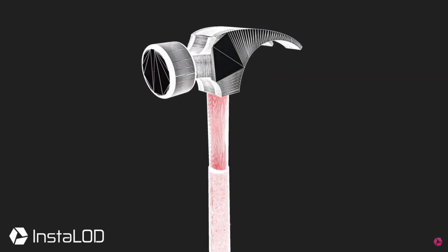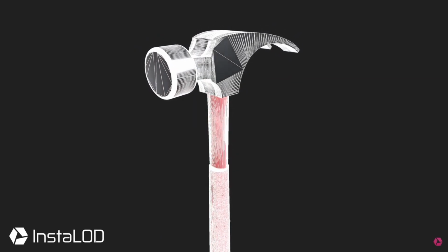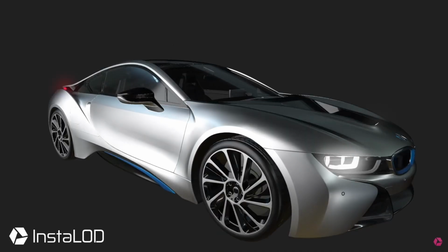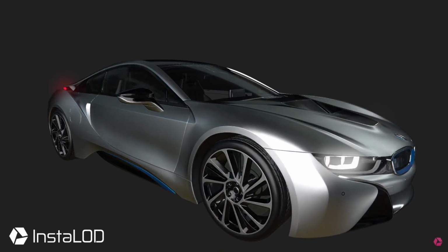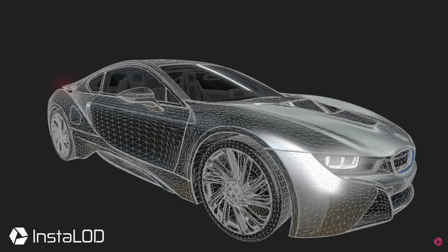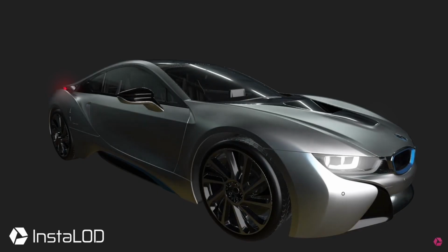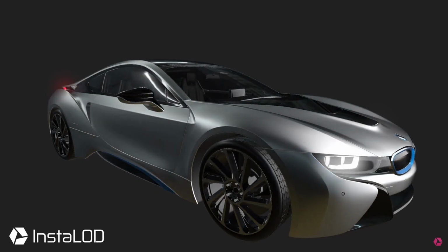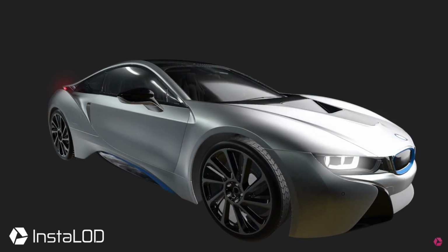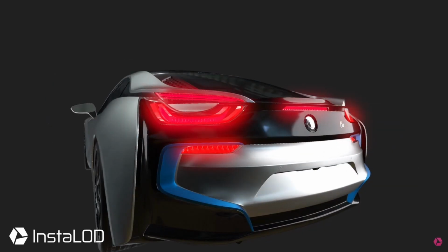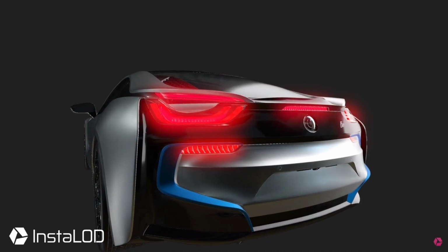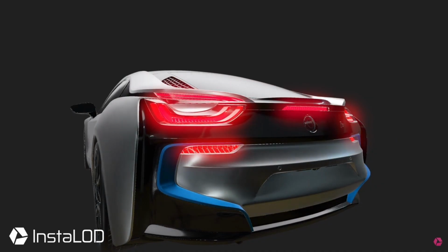millions of polygons. Tessellation quality of CAD meshes can also vary greatly between tools, resulting in common issues like broken UVs and unseamed or unbridged CAD patches, which lead to drifting or swimming in the optimized asset or even invalid normals. All of these issues make it very difficult to establish a clear workflow on how to bring these assets to life without recreating them manually.